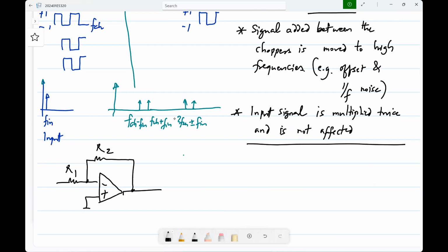You understand the problem, right? R1 and R2 are slightly different from each other simply because of random mismatch. They have nominally the same value. Now, we want to make the gain exactly 1 and we are willing to use dynamic techniques. And dynamic techniques by implication means that the signal is at low frequency. This dynamic variation will happen at some higher frequency, which will be averaged out by later filtering, whether inserted deliberately or already present in the system.